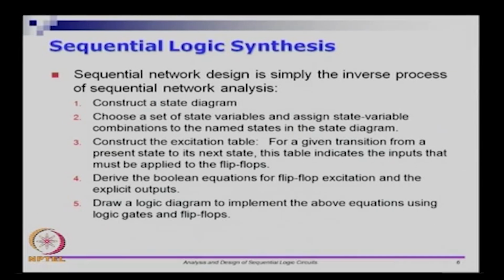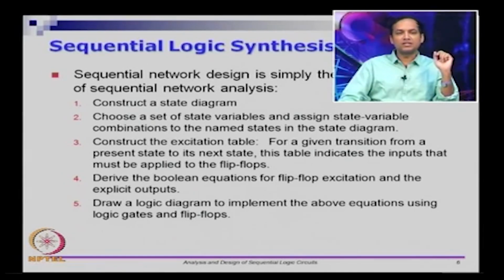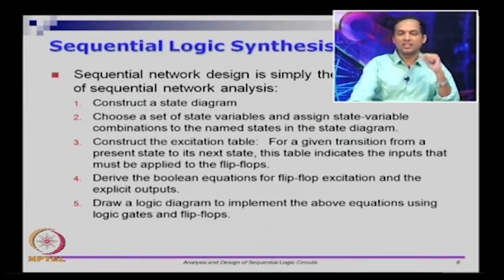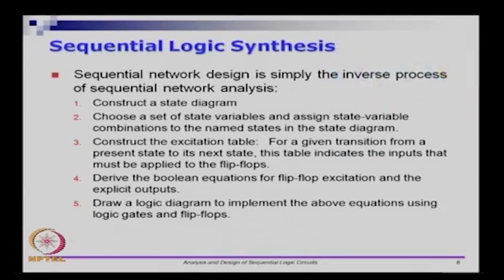Then whenever you are told to construct a circuit, if you are going to synthesize a state machine, you should also be given constraints on what flip flops you can use. So, use the flip flops excitation table and derive the transitions and get the Boolean equations for it and draw the logic diagram. So, these are 5 different steps, but we will see them one after the other in a little while. This slide is there so that you can go back and look at the steps and see how to do it for a problem by yourself.